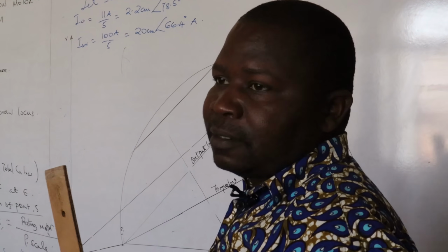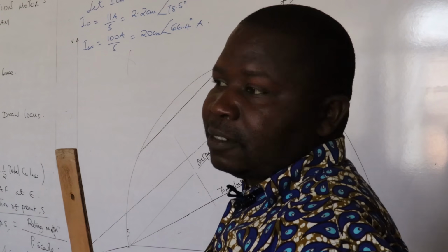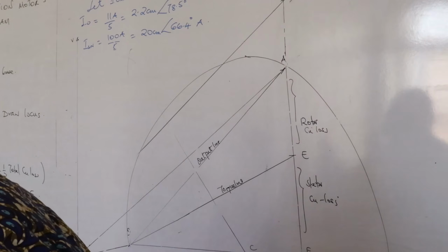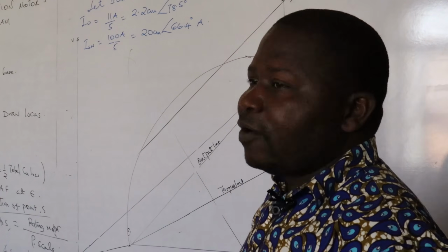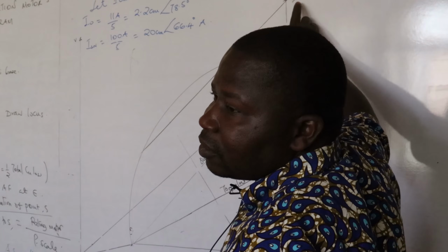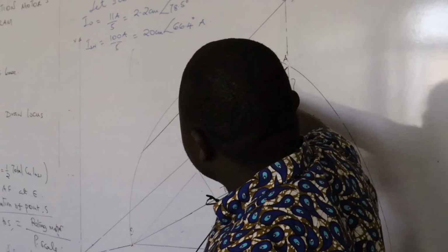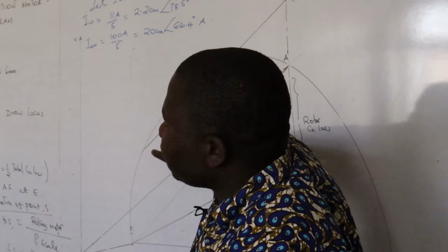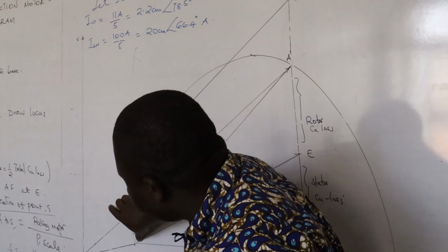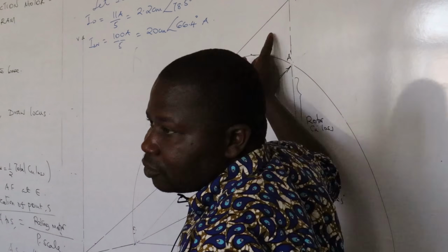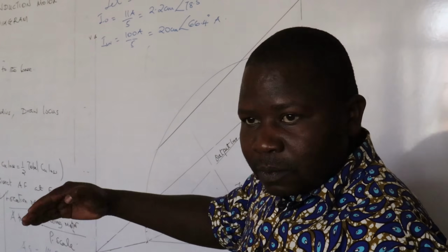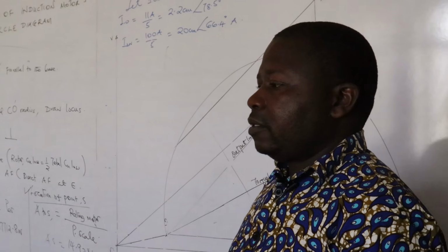I don't want you to use the set square. I've said this is high level work. You know the value here. So with the compass, stand anywhere on the output line and mark. You can even mark 3 of them. Then join those points. You will have a line parallel to the output.